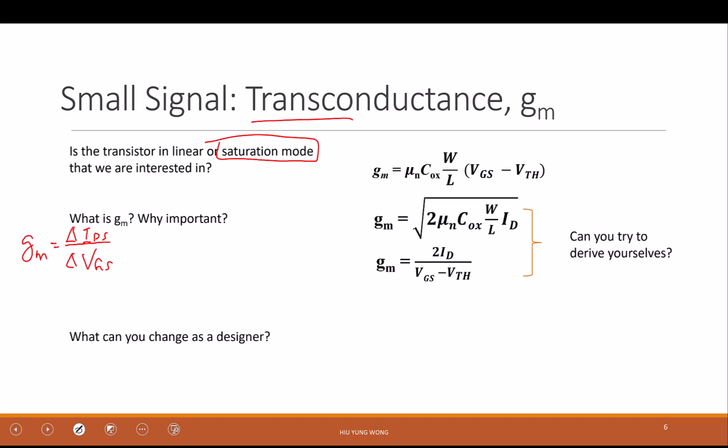We're talking about, I turn on the switch on the wall, how much current will flow through the lamp, the light. That is the transconductance. I do not directly touch the light, I touch the switch, right? Something like that, okay? Which is just equal to the partial derivative of IDS with respect to VGS, right? And what is IDS?